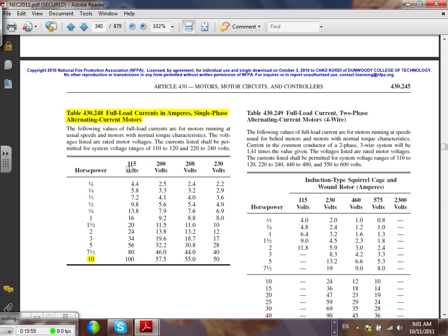Look how ugly that would be. My voltage is 115. The amps of a 10 horsepower at 115 is what? 100 amps. So Ashley, my friend, the whole panel that you have in your house will be dedicated to feed just one 10 horsepower motor. That's why, guys, we go three phase after that. The amps go so high on them. So 115 is high. Because it's 115, it's high, I'm going to burn it at 230. How many amps can you get at 230? Almost half. Double the voltage, you get half of the amps. Can you guys see the relationship?